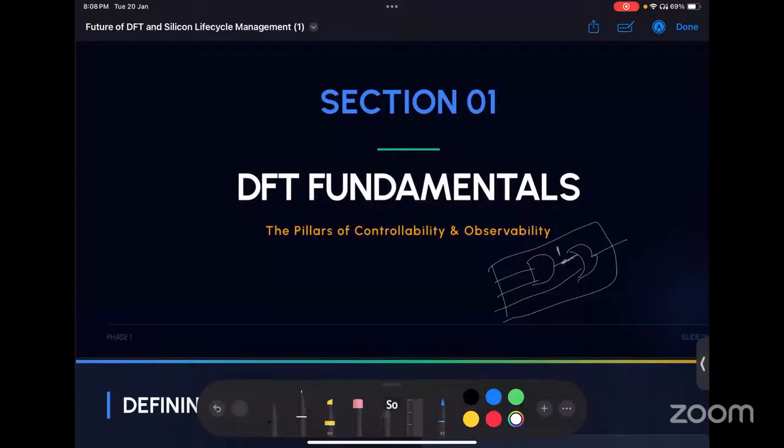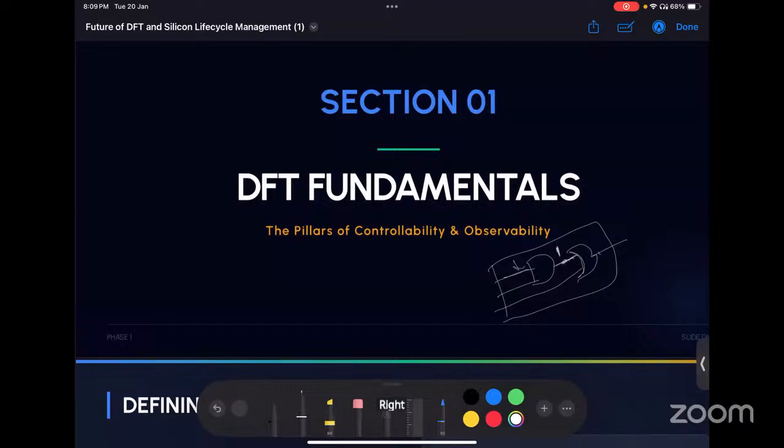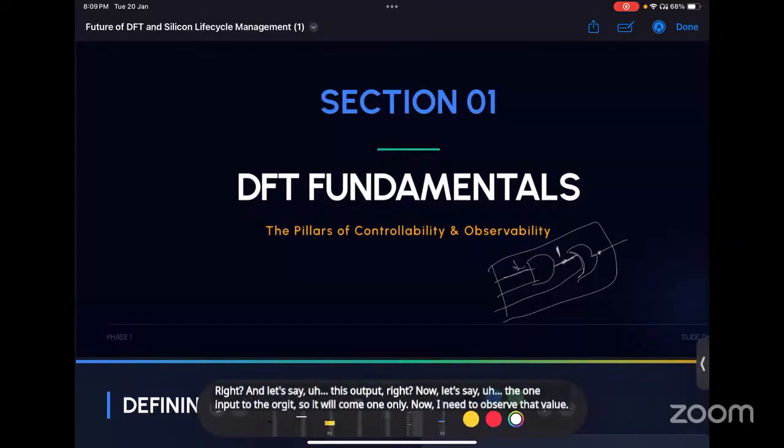The AND gate fault sites are basically two inputs and one output. This is called the fault site or nodes. So let's say we give one value here. That means I'm controlling that node of the second OR gate here. With one input to the OR gate, the output will come as one only. Now I need to observe that value at the output.